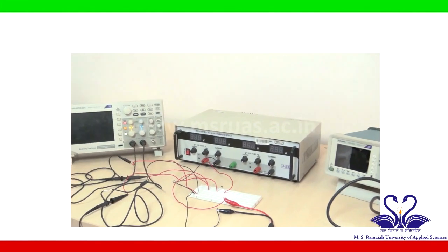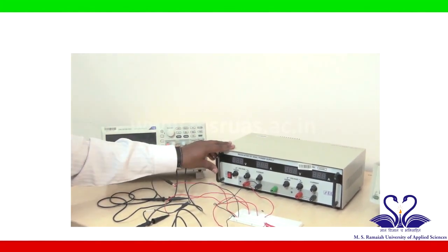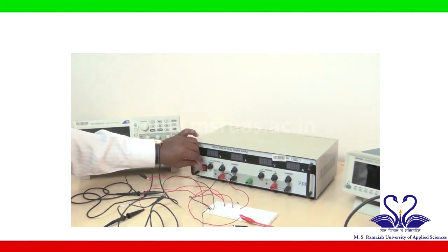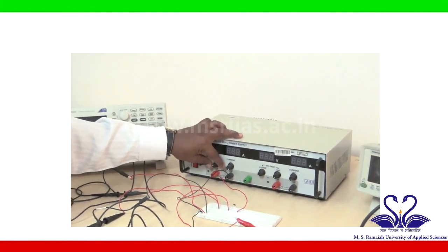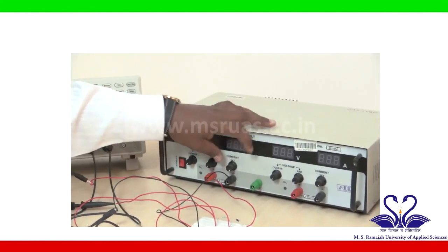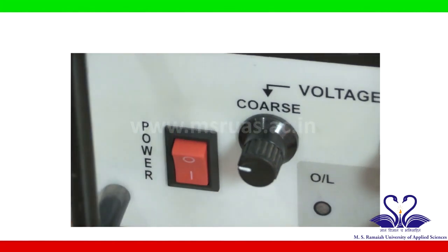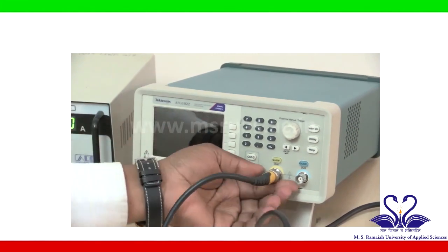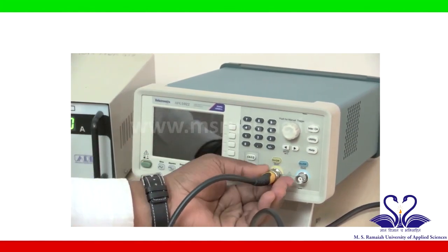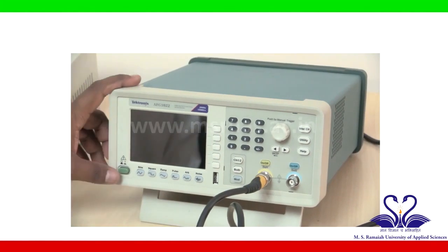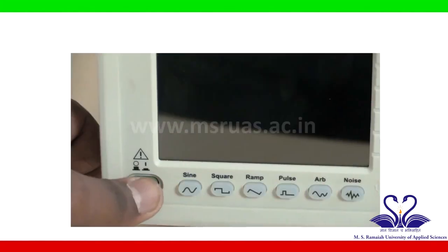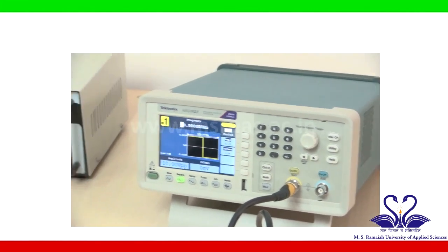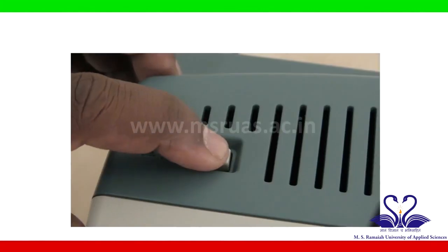Now, let us switch on the equipment which I used here. First, the DC dual power supply. Before turning it on, make the voltage minimum and the current maximum, then turn it on. Similarly, before turning on the function generator, just check whether the probe is connected properly or not. Turn on the function generator. Turn on the digital oscilloscope.